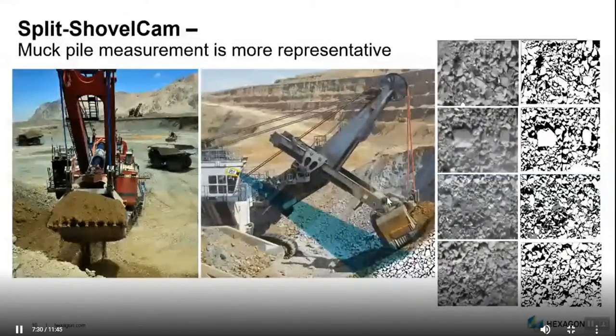And I'm going to talk a little bit about our automated system. You kind of saw a highlight there on the shovel cam system. This is where you have cameras mounted on the shovel looking at the toe of the slope. Generally speaking, we're getting one pass for each bucket load as we go to fill a four-pass shovel, four-pass truck. So this gives you an idea that the x-axis here is about 5 meters and the y-axis here is about 4 meters. So it's quite a large area to get a representative sample of the post-blast fragmentation.